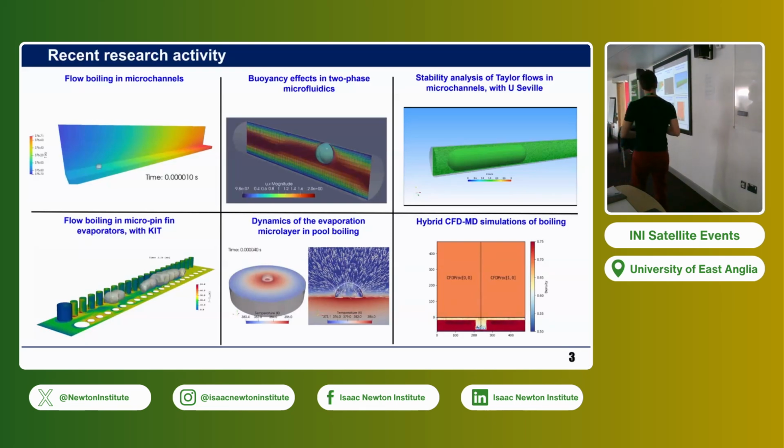So you can use OpenFOAM, you can use Basilisk, you can use the most sophisticated CFD software ever, but you always need to seed the bubble. The bubble will never be born naturally if you use traditional Navier-Stokes equations. To have the birth of that bubble, you need to be able to capture somehow the statistical fluctuations that give rise to the birth of the bubble.